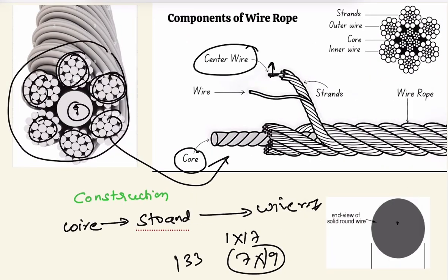So you understand. The aggregate effect of a number of wires together increases the tensile strength, and due to frictional contact and the slippage between the wires, it is not acting as a single body. It has low twisting and bending forces. So this is clear up to now.